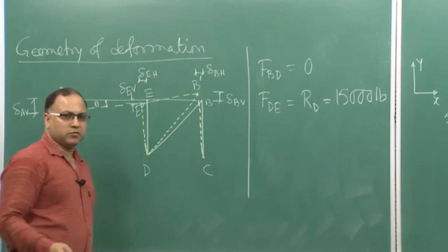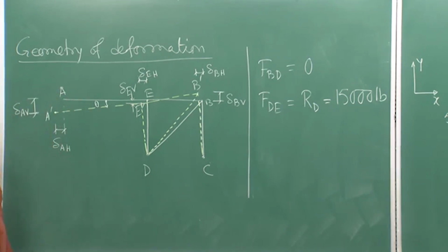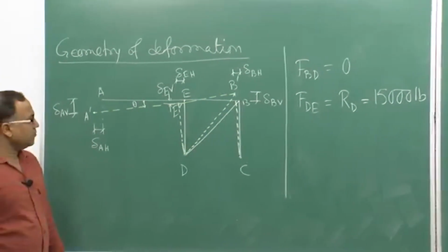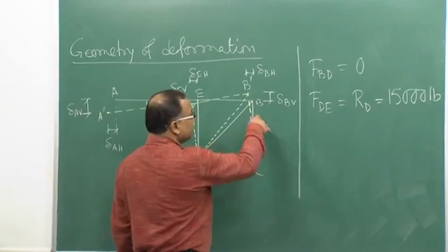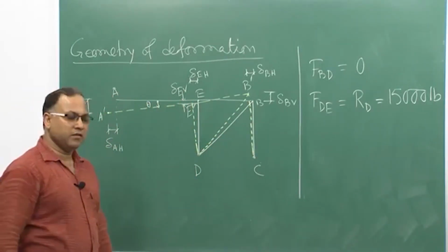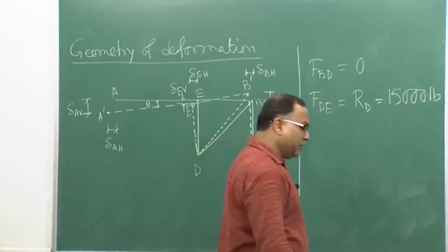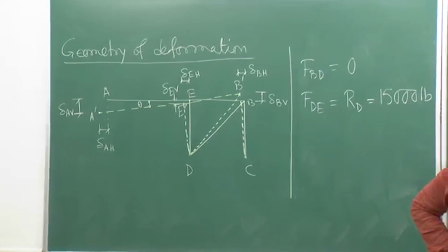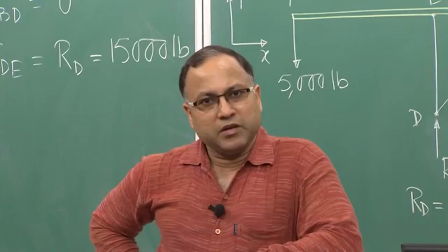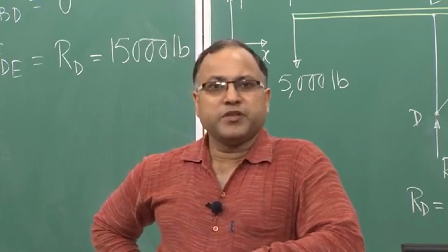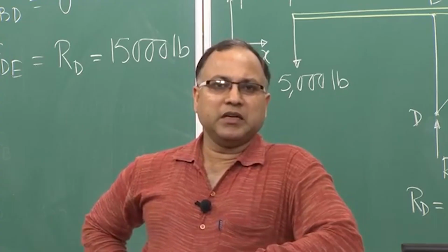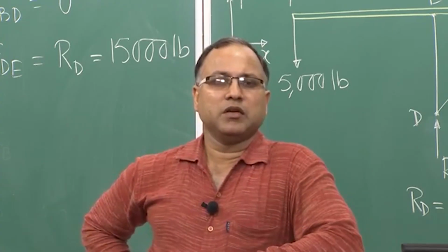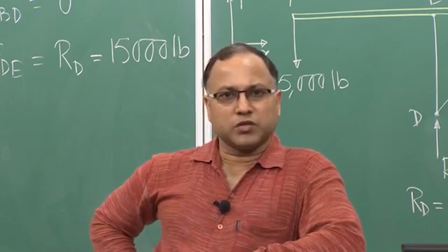It is quite understood that those members are there. Member BD is not carrying any force, so there is no deformation in that member, because deformation happens only if the member carries some force.